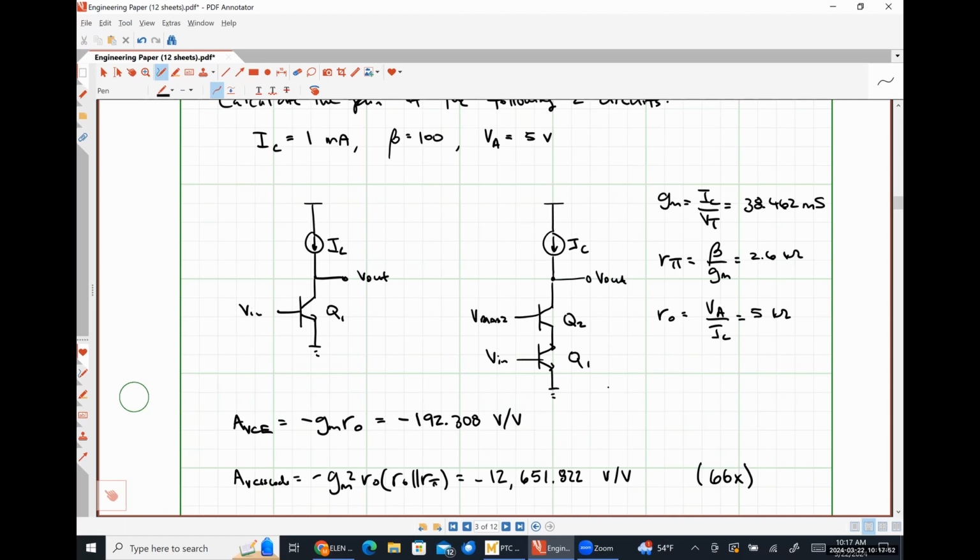So we get larger voltage gains, but we also eliminate headroom and we increase the probability that our gain is so high that it's going to actually push the device down into not the active mode of operation during at least part of its swing.